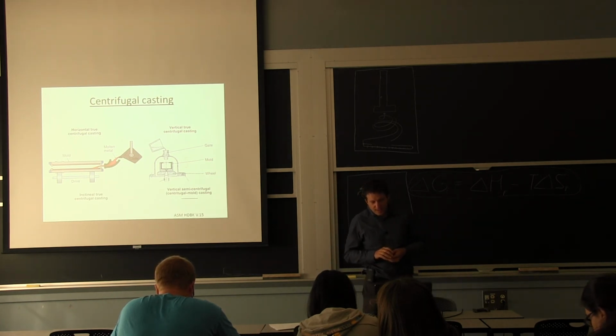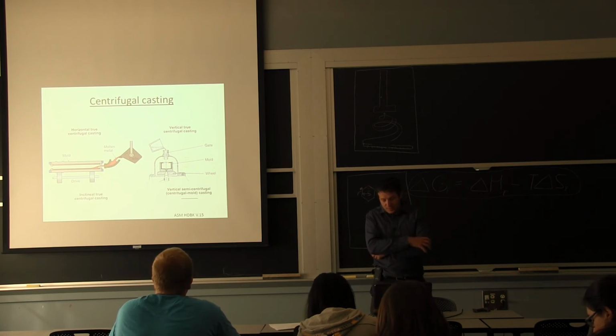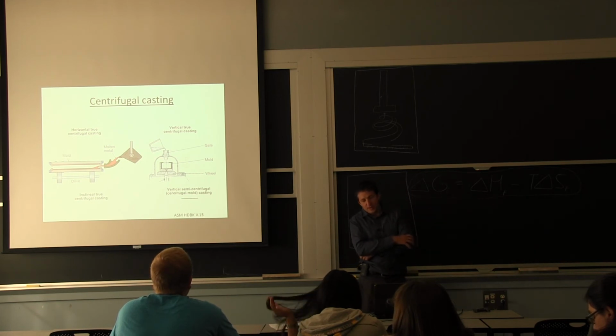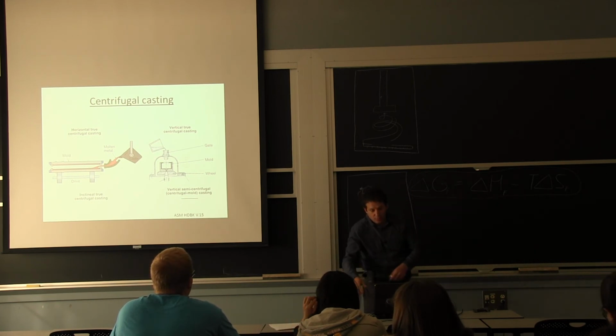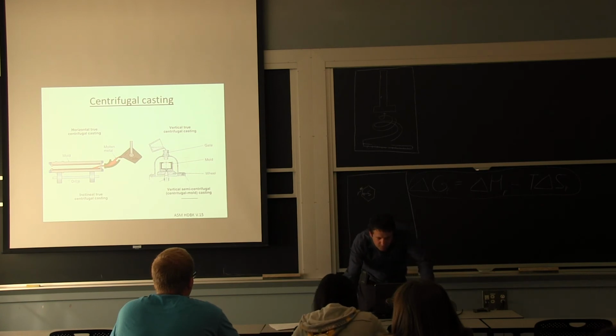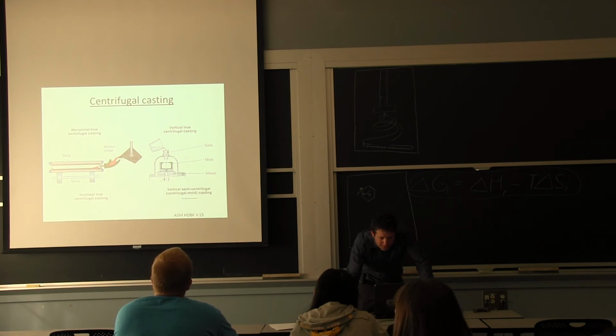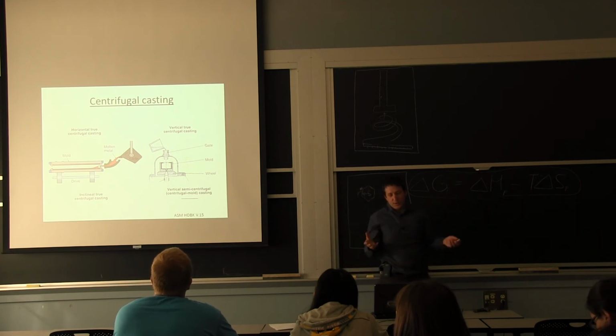Centrifugal casting is something that is used in jewelry. One of the advantages, obviously, is it's fast. There are different ways of doing it, but the way I've seen is, say the axis of the whole centrifugal machine would be right here. Off center you have your molten metal that you can pour into your riser system, and it gets injected into your parts.